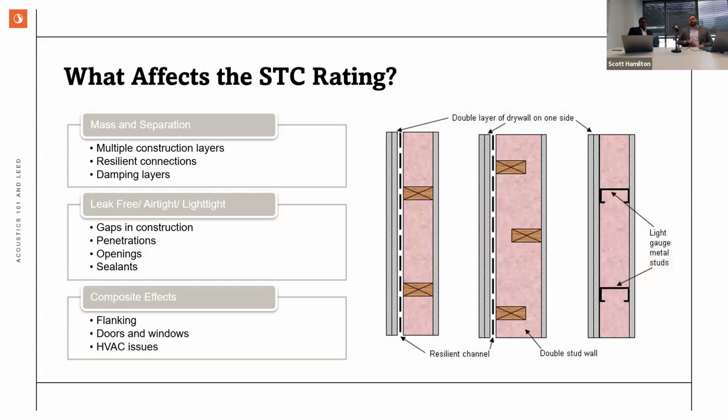And that all also then comes down to we need air tight construction. So we're also trying to seal everything up, everything that's coming in. We're trying to make sure that we don't have rigid connections across anything that is resilient. And so you'll see us dealing with like MEP penetrations of how do we bring in the ductwork and not compromise the wall.